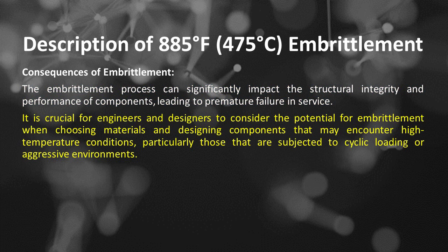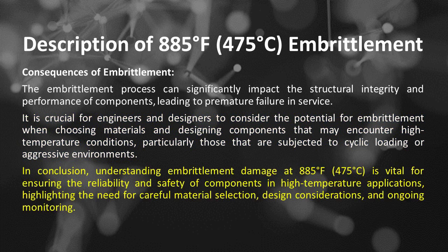It is crucial for engineers and designers to consider the potential for embrittlement when choosing materials and designing components that may encounter high-temperature conditions, particularly those that are subjected to cyclic loading or aggressive environments. In conclusion, understanding embrittlement damage at 885 degrees Fahrenheit or 475 degrees Celsius is vital for ensuring the reliability and safety of components in high-temperature applications, highlighting the need for careful material selection, design considerations, and ongoing monitoring.